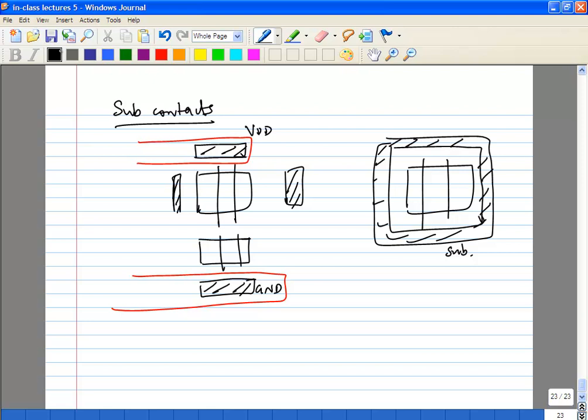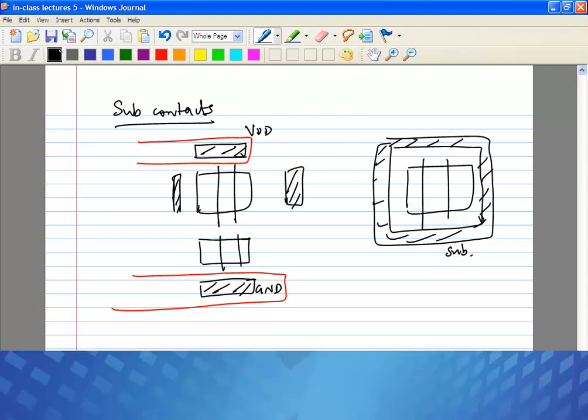If other transistors share the same substrate, they can pick up this noise through their substrate, and that's one of the reasons why you're trying to give this substrate contact, because your substrate at the end is going to be connected to a central ground somewhere else far away. So you want to give it a very short local ground, because what will happen is this will be running on metal.